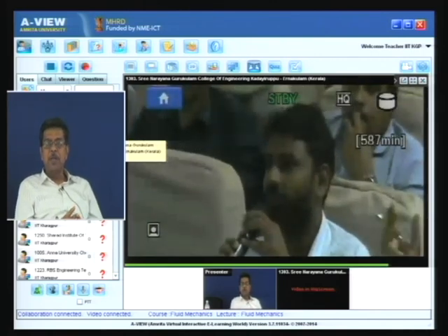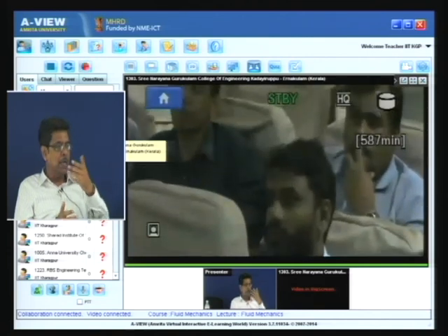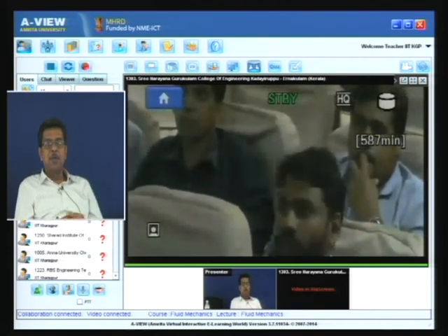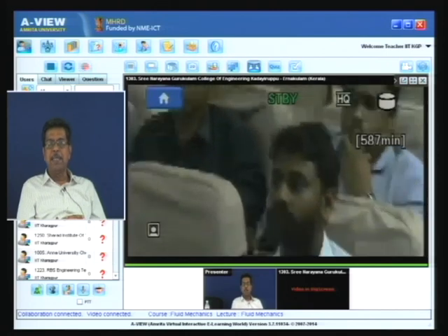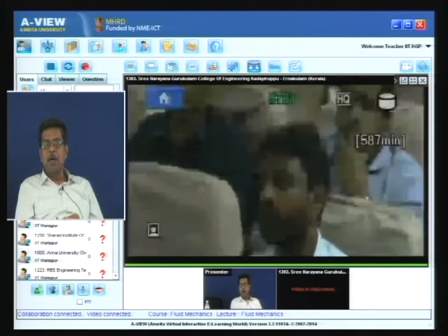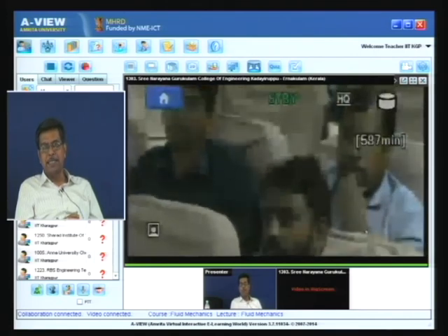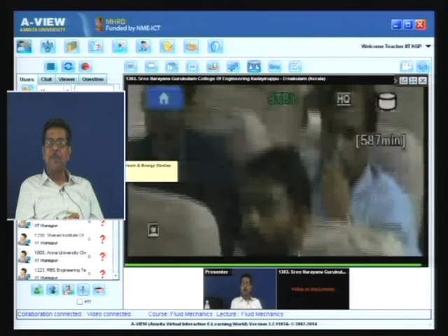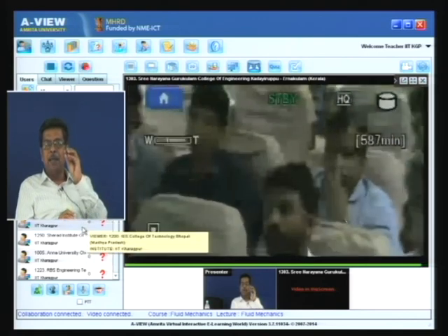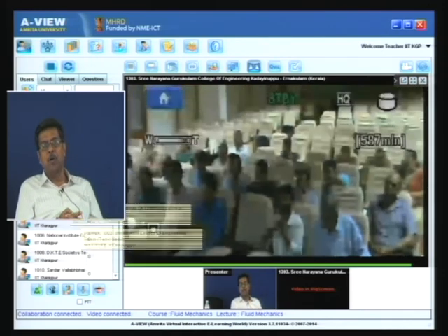Please listen to me. The continuity equation is derived with respect to a control volume, because there is a mass flux coming in and going out. This is not a system approach. Whenever we consider an element of fluid, that is nothing but the elemental control volume.